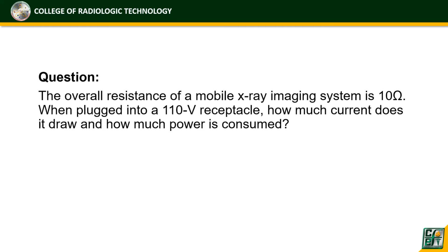Third problem: the overall resistance of a mobile X-ray imaging system is 10 ohms. When plugged into a 110 voltage receptacle, how much current does it draw, and how much power is consumed? So there are two questions to be answered. How much current does it draw, and how much power is consumed? So let us answer.